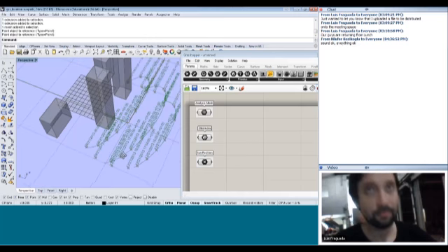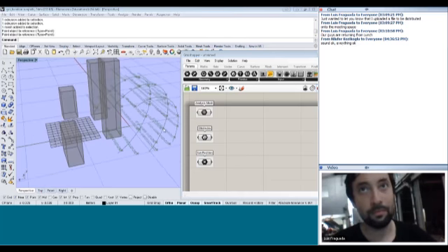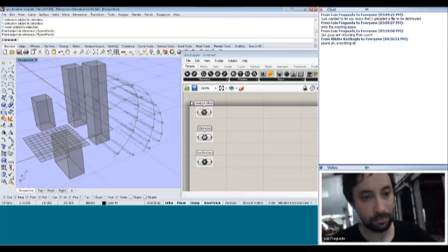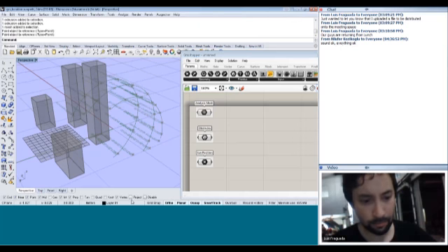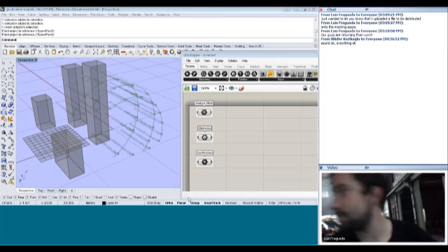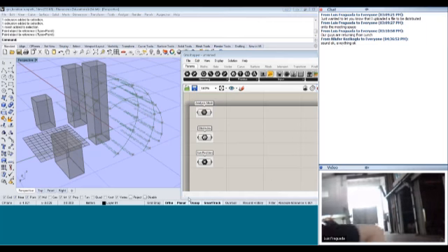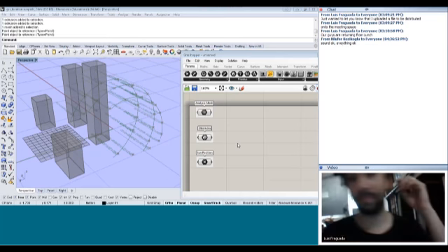You have to shift, select all the points, right click and set multiple. So that is all. And point. Yes, you have to create all. So can you select the component and say you want to give it a name? Select the component and hit Control P. Yeah. All the points. Right click.